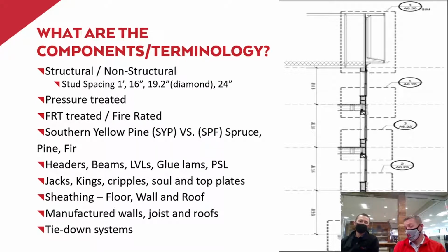Absolutely. And if you're talking an exterior wall, it might have 60 ring shank nails from top to bottom holding that thing in, and you're going to spend the better part of a day trying to strip this out, building temporary walls if it's under heavy load. It's something that you really have to pay attention to in your framing process.